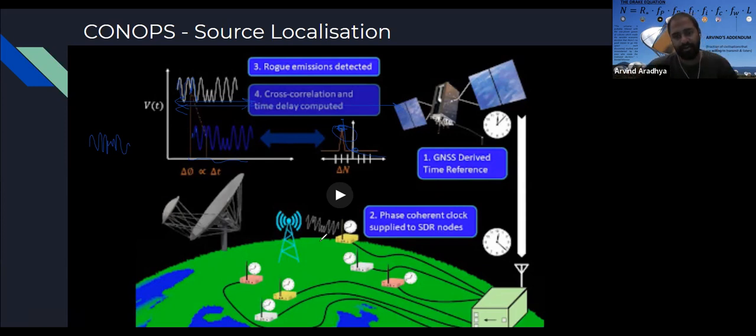It's the fact that currents running in the motherboard, any changing current radiates, which is why lightning is a radiator. Any wire that has a varying current versus time will radiate waves. So your laptop is not a shielded box. There's a lot of gaps in it. Your circuit board, whatever the traces are on a PCB, act as antennas for some frequency and then they radiate. That's called EMI, and telescopes are really sensitive to this.